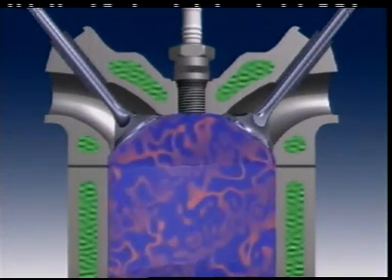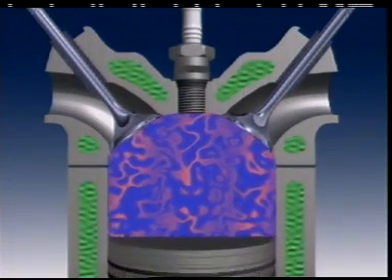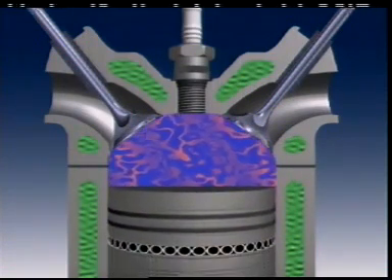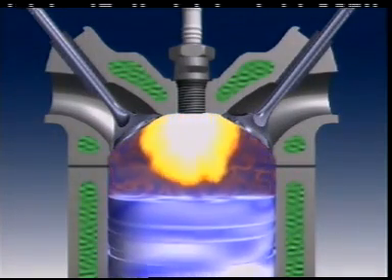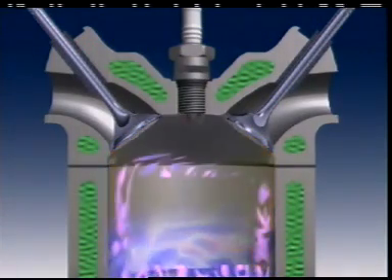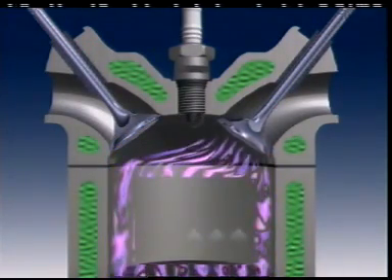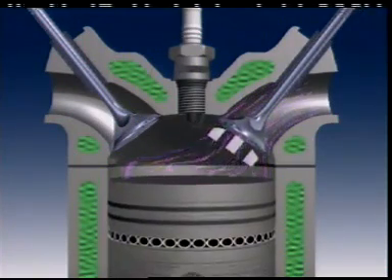When combustion occurs in the cylinder, the walls, piston and piston rings are slightly cooler than points closer to the burning mixture. Some of the air and fuel molecules come in contact with these cooler parts, and they cool down until their temperature becomes too low for combustion to occur. They are left unburned, and when the exhaust port opens, they leave the cylinder.